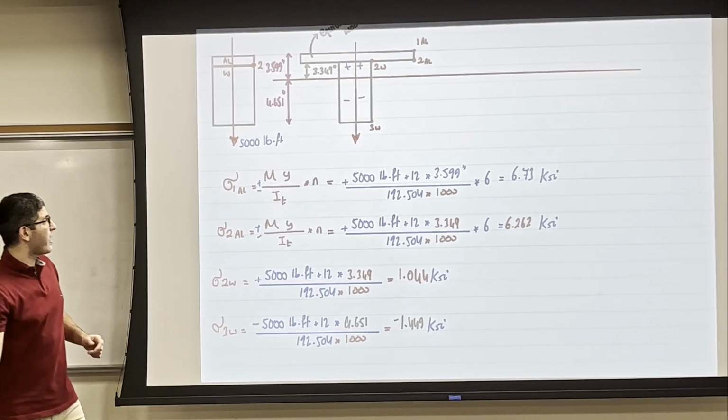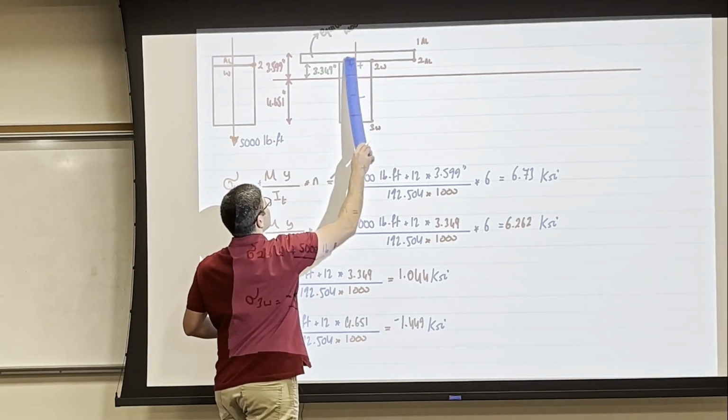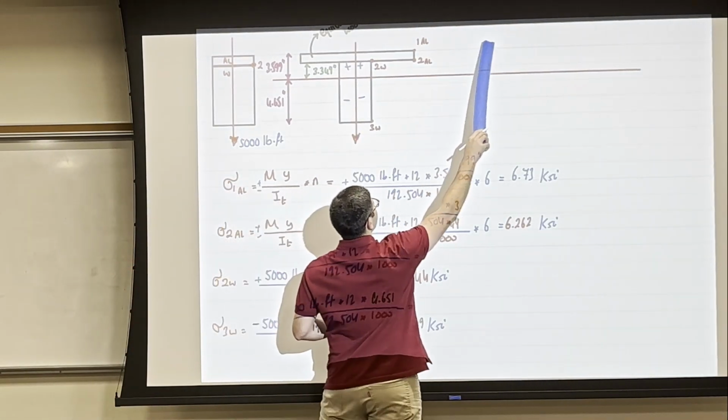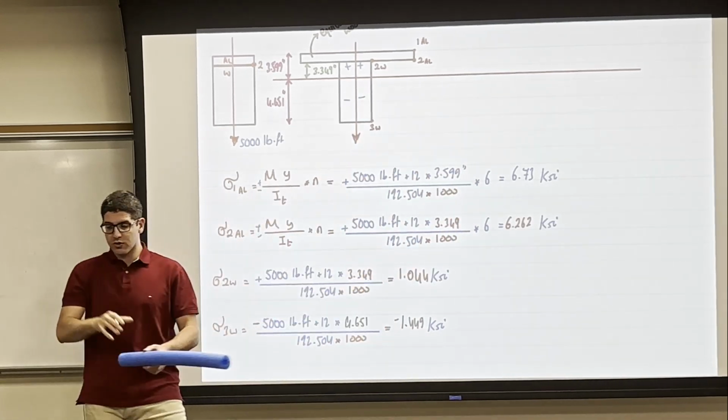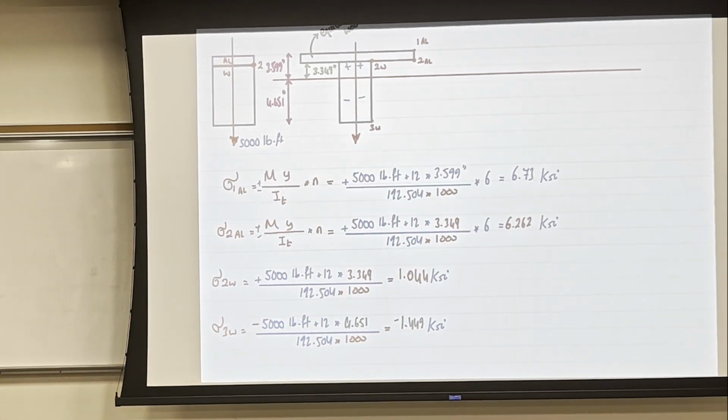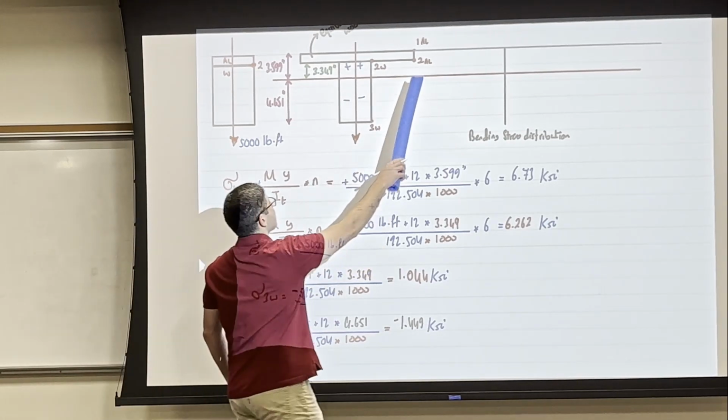Since we have the moment vertical, I'm going to draw the reference line here, and the stress distribution is going to be vertical as well. So here is called the bending stress distribution, and I'm going to draw the line which indicates where I want to calculate the stress. For example, I draw this line because that's at point 1.